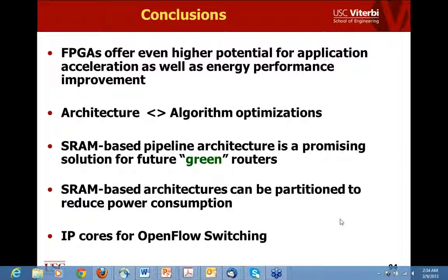In the early part of your presentation, you talked about cascaded FPGA logic. And when, for example, implementing the add or other circuits, you asserted that they were constant time algorithms, but it seemed that, for example, the number of gate closures that you had to traverse were linear in the number of bit positions, and so it seemed that there was a certain non-constancy in the solution time for some of those algorithms. So I was trying to get a little better handle on the assumption that leads you to those constant time results. Right. That's a very good question.